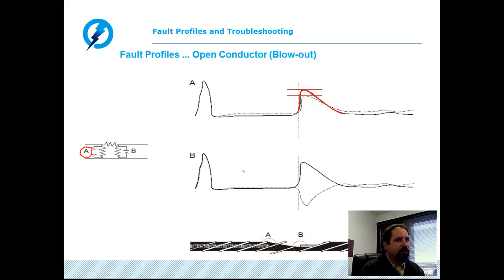Now, during the high voltage arc reflection test, when we're sending breakdown voltage to the fault, if the gap is very, very large, we may not get a strong magnitude arc that in essence will drive the impedance to 0 ohms. But the presence of the high voltage discharging through the fault, even though the gap is quite large, will lower the impedance some amount.